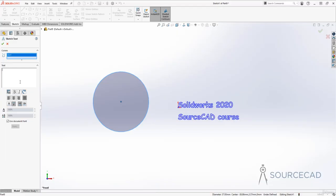Let's now type text here. So SolidWorks Professional 2020. All right, and that's our text. I'll just add single line of text here, and as you can see, this will be distributed completely along this path. Now why is this happening? Well, that's because of one of the formatting options that we have here, and that's this last one. This is full justification. So I'll just justify it towards left, and that's what we have.